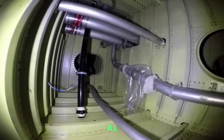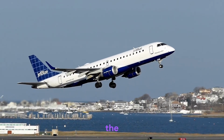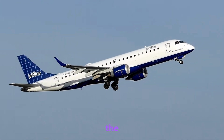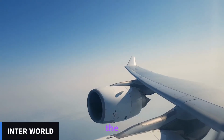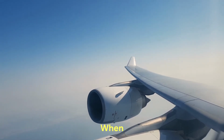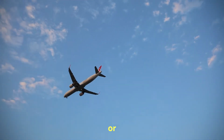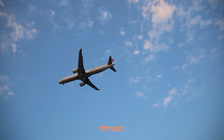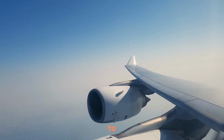After the takeoff, next comes the climb phase of the aircraft. As long as the engine's thrust is more than the drag, the speed of the airplane will keep on increasing. The greater the speed, the higher will be the lift force. This will cause the airplane to go up. When the airplane reaches level flight, there won't be any acceleration or change in altitude. You can see that with this condition, the thrust should be exactly equal to the drag, and the lift should be exactly equal to the weight of the airplane.